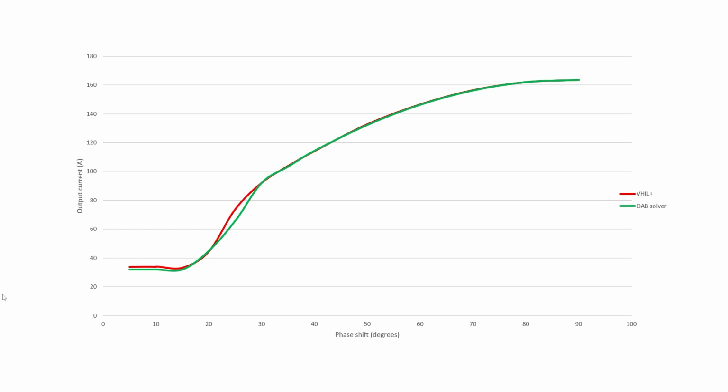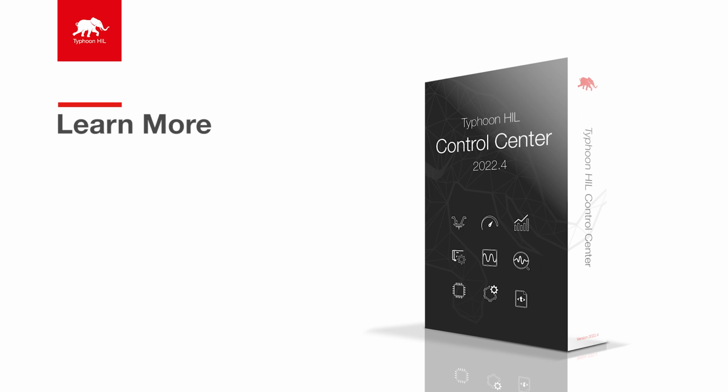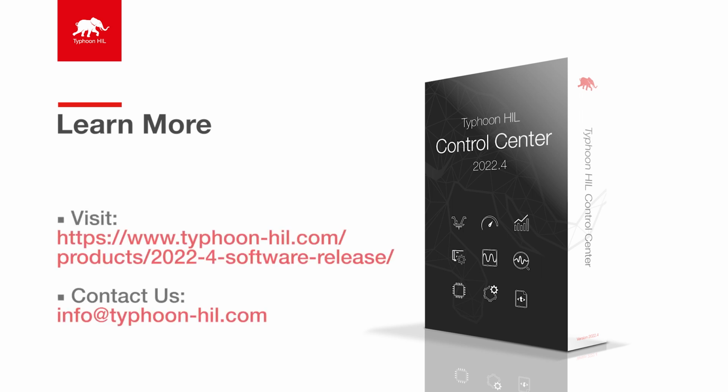We can see that by using the dual active bridge converter solver, we get very similar results in real-time simulation as those that we can achieve when simulating in non-real time with a smaller time step. We hope that this new dual active bridge component will help you develop for high-frequency control applications, and we look forward to your impressions.